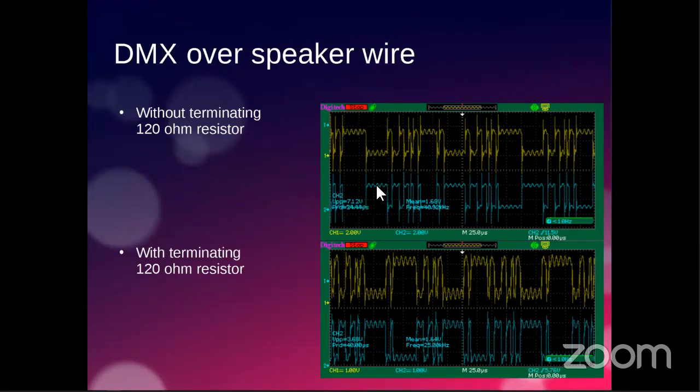The other thing is if there's interference in the wire, the interference tends to impact both signals, but in the same way. And so consequently, the difference remains somewhat constant. So even though there's a lot of ripple going on here, the ripple tends to be reflected on the other end. And so the difference between the 2 signals does not change, despite the fact that there's interference that's been introduced into the circuit, right? That makes a big difference to the ability for the device at the other end to receive this signal.